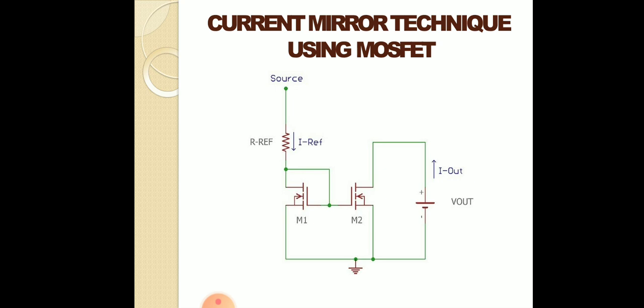If the drain to gate voltage VDG is 0 for the MOSFET M1, the drain current of M1 will be therefore f(VGS, 0) equals IN. Thus, IN sets the value of VGS.